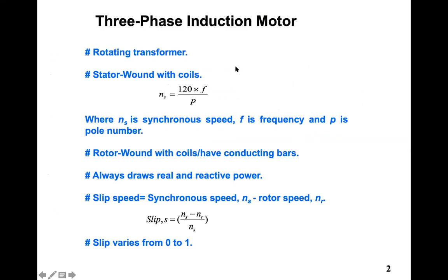Okay, so therefore in this case also there will be two sets of coil, one on the stator, one on the rotor. I am showing you the picture on the whiteboard. And in this case, everybody remember, in case of induction motor or induction generator, there will not be any physical poles that I discussed just now. That salient pole, non-salient pole, those are the physical poles. Those are the real poles. But in case of induction motor, there will not be any physical poles. You have to create poles with the application of the voltage.